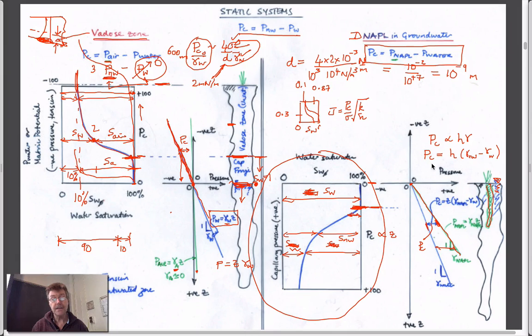And so if we can link capillary pressure to this, then presumably, since we define a J function as this, you could rearrange this expression in terms of capillary pressure as a function of J on one side of the equation. And you can basically take this capillary pressure versus saturation curve, anchor it at the surface, and then physically stretch it so that it comes to the appropriate coordinates on the system. And that would be your saturation versus elevation profile in your system. That's what we're trying to do. And that's basically one component, not maybe of the third assignment, not of the second assignment.